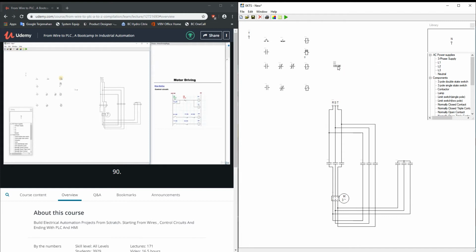Now let's create this portion because it's the easiest. This is the timer coil. This is my second contactor and third contactor. Okay. Now I need to connect the phase to all of these. You need to give phase to the first terminal of all of these NOs and for the start button.